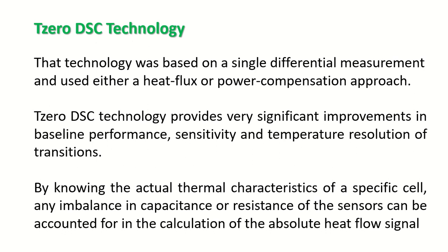The improved performance results from a cell design which produces two simultaneous differential measurements and provides the ability to calibrate the thermal resistance and heat capacitance of the individual sensors as a function of temperature.